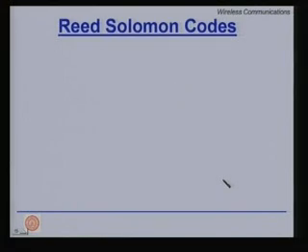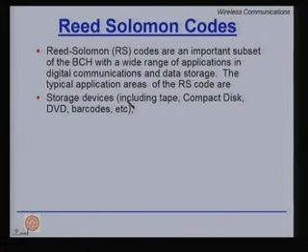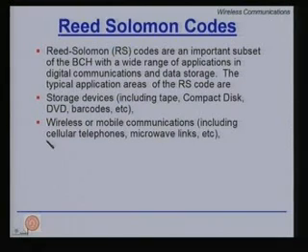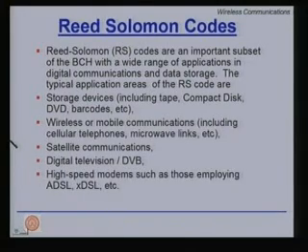Now, let us go into a subclass of BCH codes called the Reed-Solomon codes, or the famous RS codes. RS codes are an important subset of the BCH codes with a wide range of applications in digital communications as well as in data storage. The typical application areas of RS codes are storage devices including tapes, your music CDs, DVDs, barcodes, wireless and mobile communications including cell phones and microwave links, satellite communications, digital TV, high speed modems.